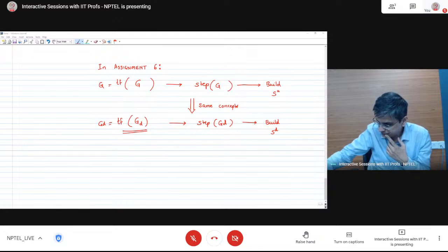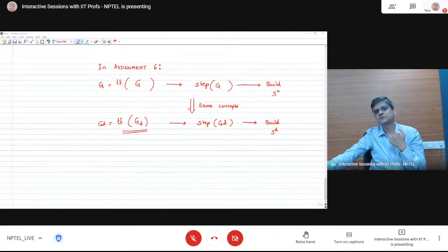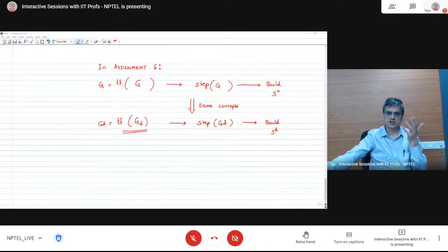Yes, the first term is indeed with the step signal. The second term is also with the step signal. As I had said a couple of times in past video lectures, measured disturbances are absolutely the same as manipulated inputs, except you cannot change the disturbance value. Nature changes it. For example, ambient temperature, you can't change it. The nature changes it.